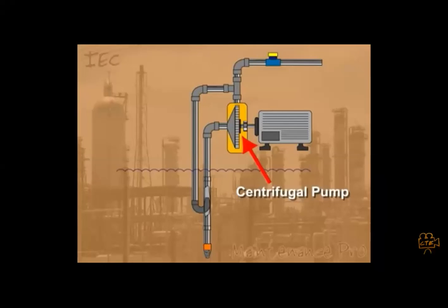What happens is we recycle, because the water which is at the top, when it is coming to the bottom, has a tremendous amount of kinetic energy. So what will happen when it is mixed with the main pipeline? It gives energy to the system, and that helps to suck the water up to a larger suction height, greater than 10.5. So that is the benefit, but again there is a drawback.